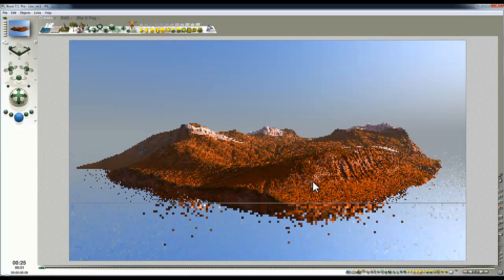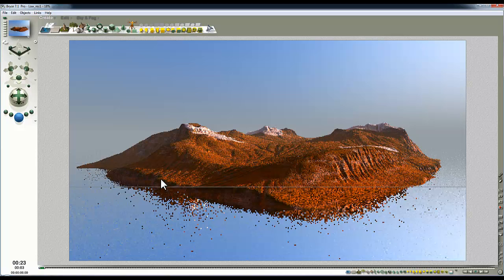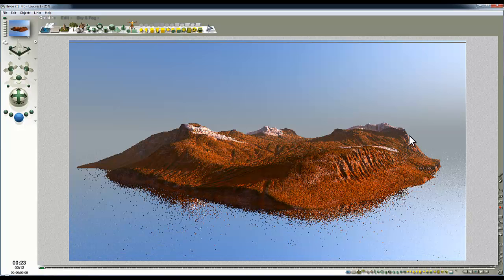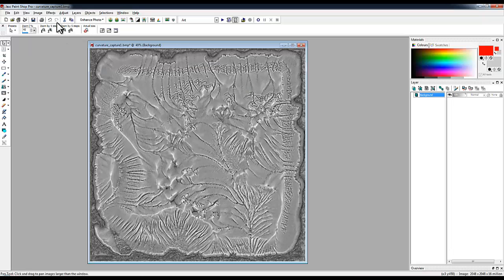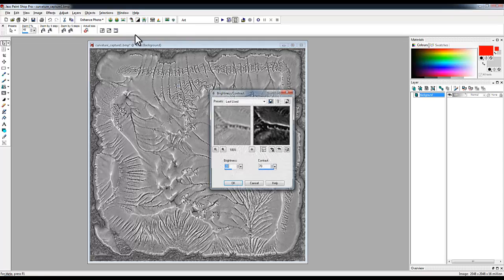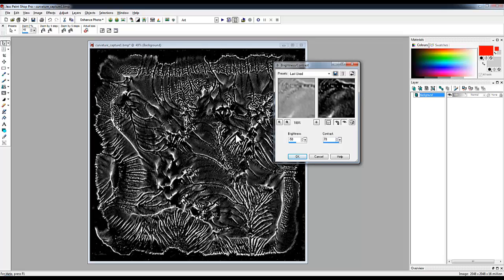So it's quite evenly blended, except for where it's arriving along this top edge. So at the moment then, because the curvature height map's predominantly grey, the effect of the curvature filtering is getting somewhat lost. So at this point what I need to do is increase the contrast of this still further. So if I go into brightness and contrast here, you can see I can modify this so that I've got preview here. We've got a lot more impressive